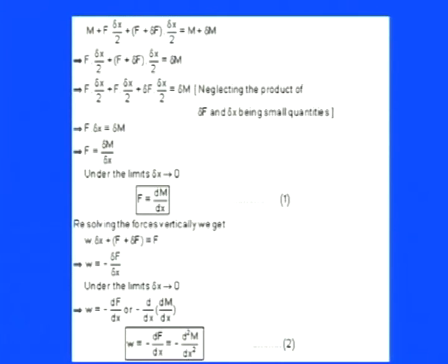Because from this relation, whatever kind of beam there is, irrespective of simply supported beam or cantilever beam, only the boundary conditions change. Whatever the kind of loading, once you take the segment, or once you know the nature of the load due to which the shearing or bending moment is coming, or how it is varying, you can simply put it in terms of force or moment and get the load.